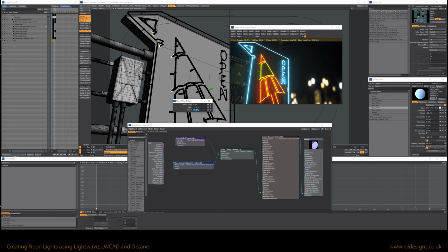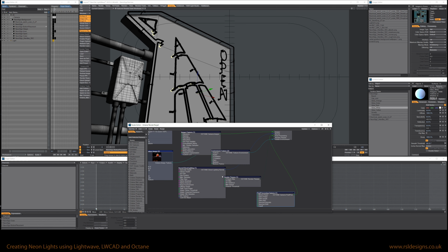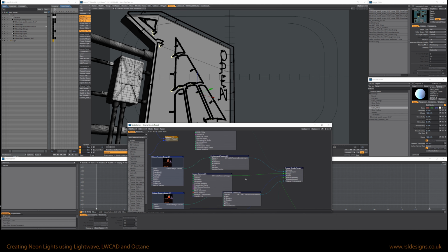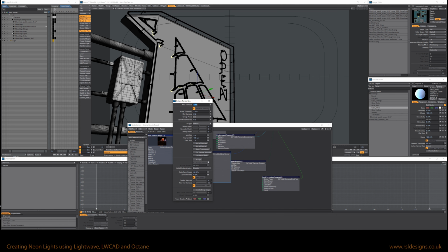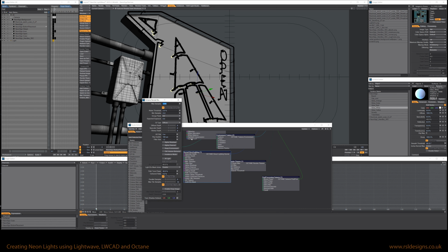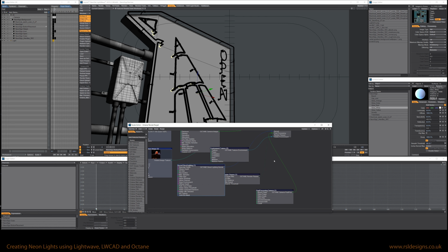And then I just distributed those between orange, yellow, and again orange, so just duplicated that one. And then I set samples to, I think it was 1200 samples, using direct lighting, adaptive sampling, and we let denoising do the final bit of cleanup for the final render.